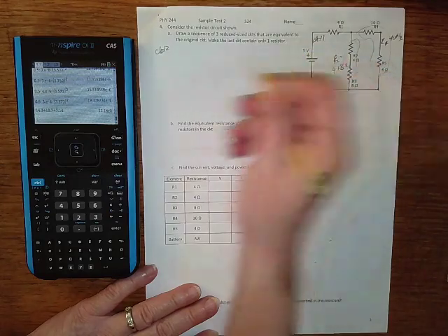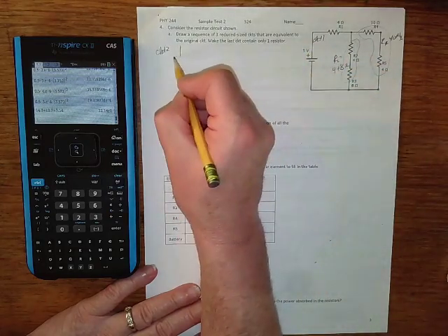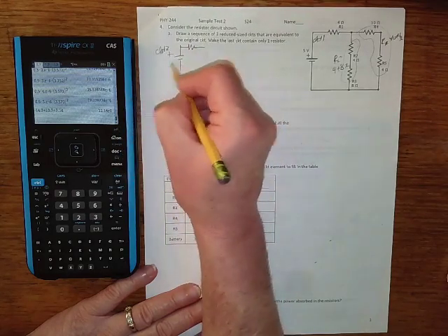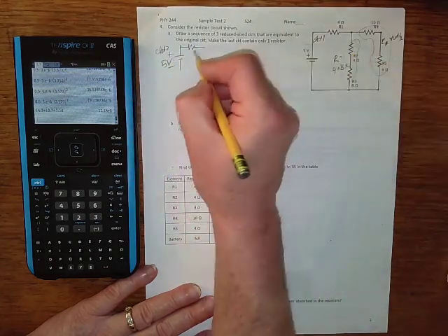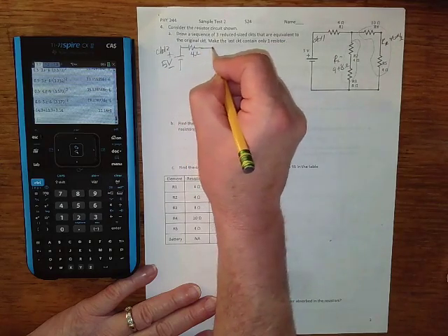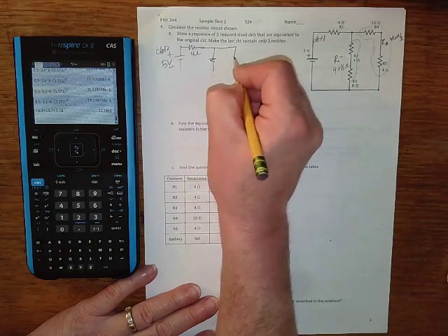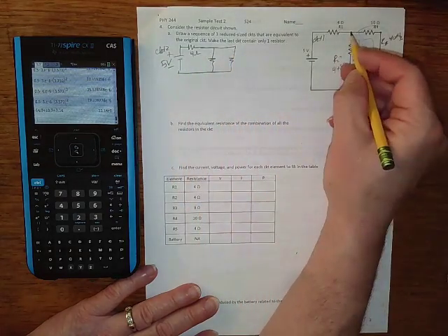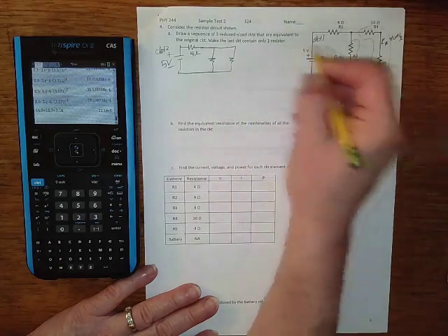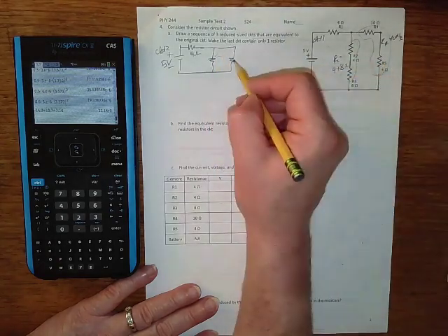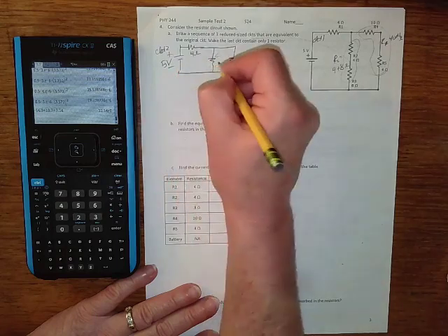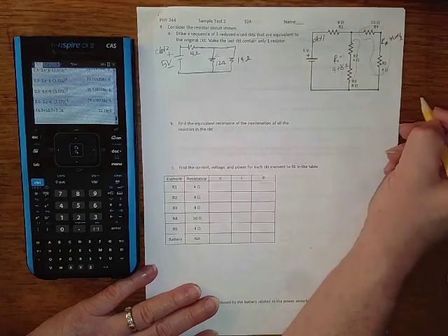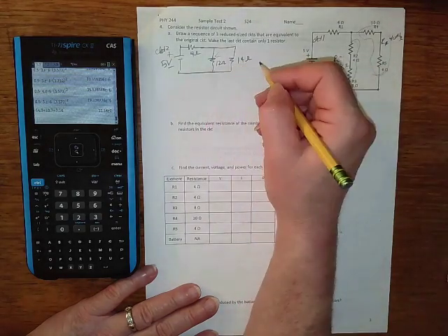maybe we're going to do 3 more, so we'll get to 4, but circuit 2, we'll keep the 5-volt source and this 4 ohm resistor here, but then we're going to have 2 resistors. This combination becomes 1 resistor, and the other outside one becomes 1 resistor, so this one will be a 12 ohm resistor, and then the outside one becomes a 14 ohm resistor. Alright, so there's our equivalent circuit.